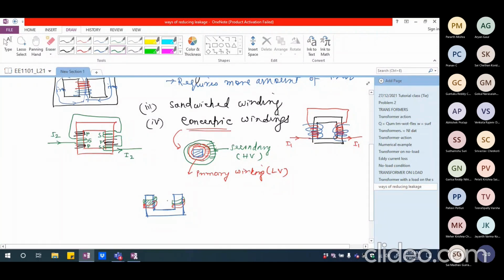Now from the top you would just put another stamping and close it after these windings are inserted. So you will have again the stampings that are again arranged one behind the other. So this is a portion of the core which is finally assembled. And this is one portion of the core which is either U-shaped or L-shaped. So you will have many cores somewhat like this.